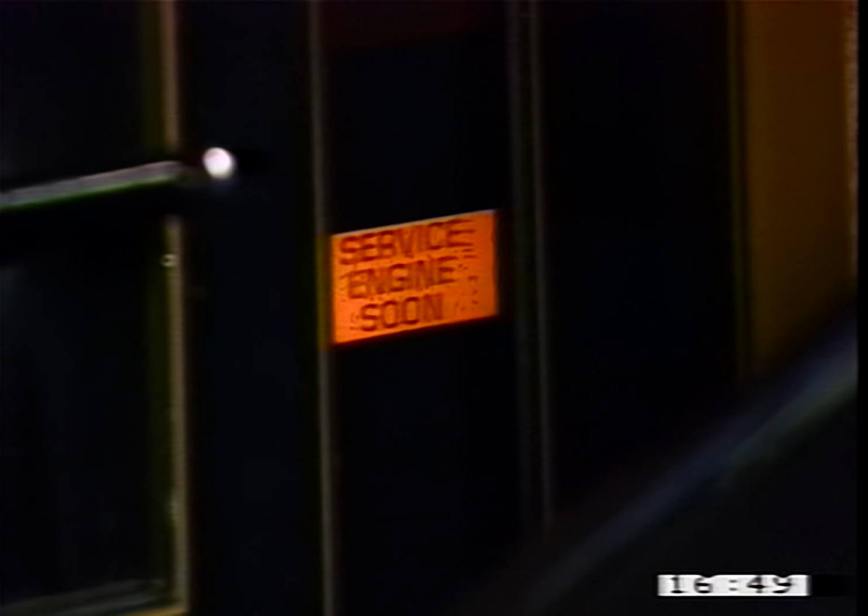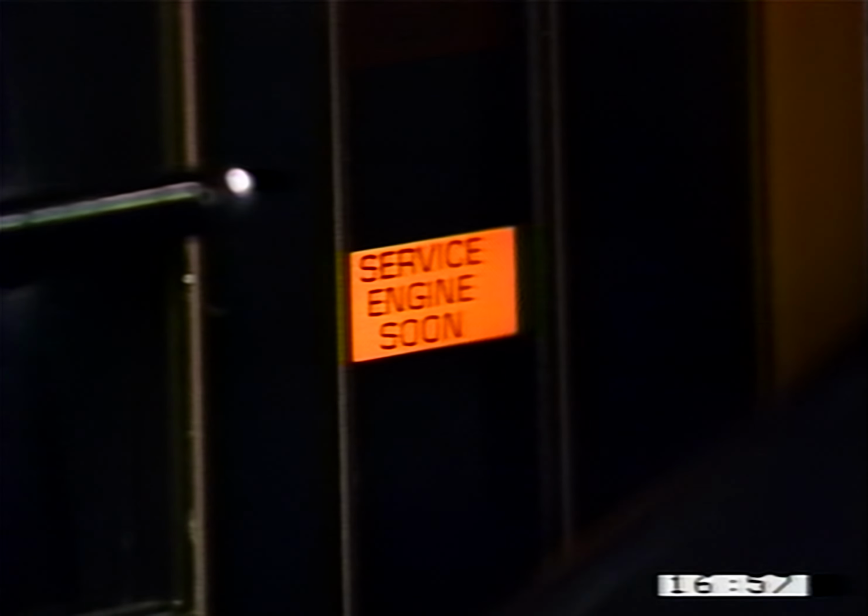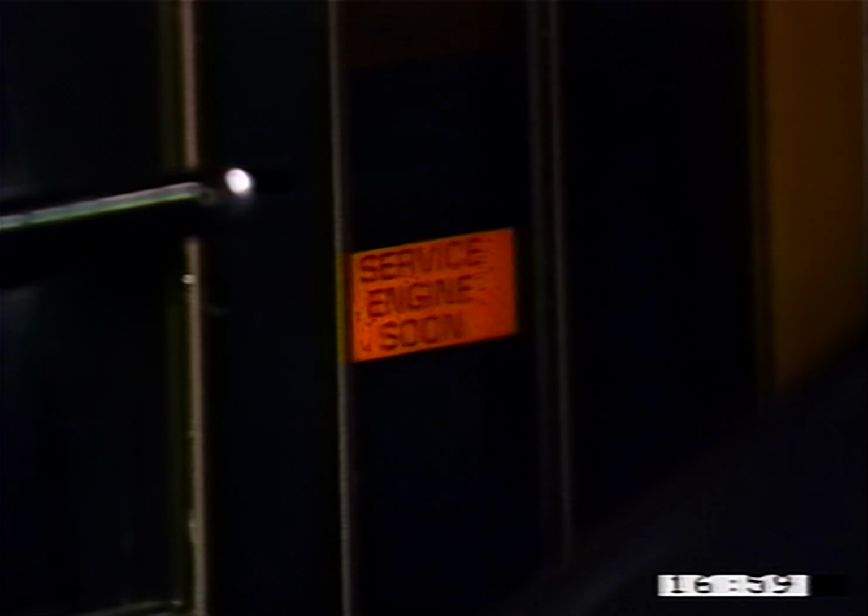A code 41 indicates that engine vacuum is available, but HEI reference pulses are not. A code is sometimes sent by either loose or corroded terminals at the 4-pin distributor connector. A code may also be set in memory during base timing adjustment. Trouble in the EST and bypass circuits are indicated by a code 42.